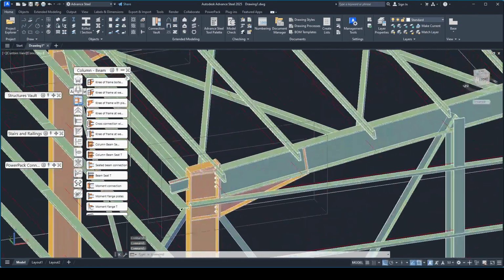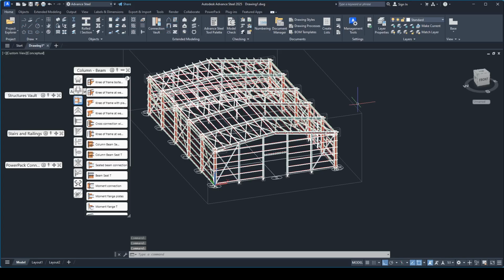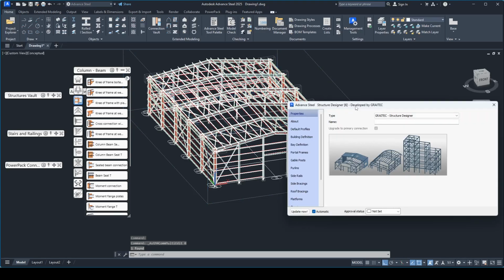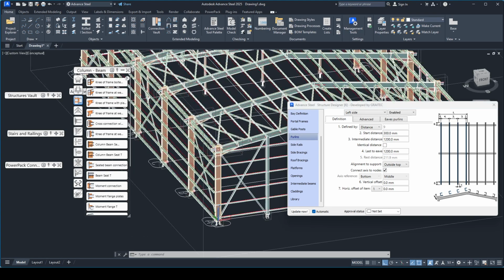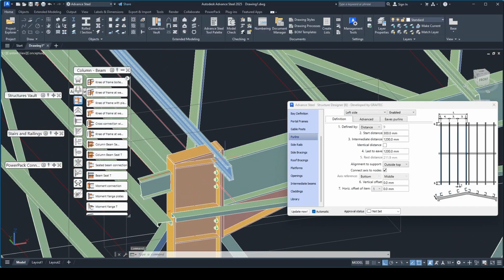Now come back, I will correct this raster. Double click on this box. Check on the Purlin. I'm sorry, it's called Purlin, not raster. We change the Purlin and the left side. Okay, alright. You can change the end stand. The last one we can change it to 1000.